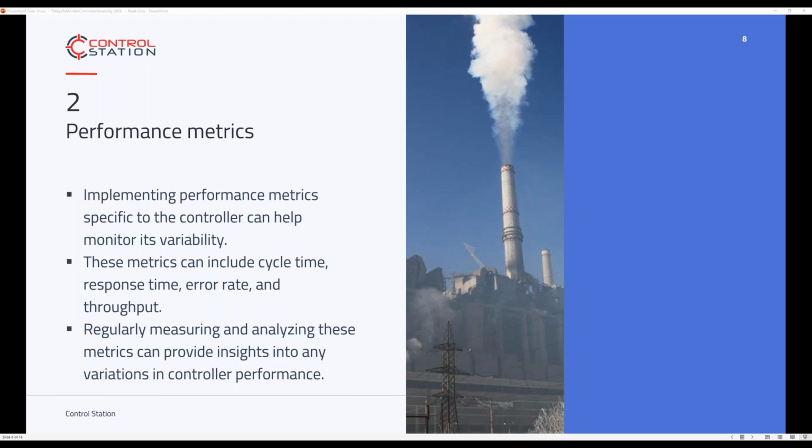That being said, we've also invested a lot of time in more advanced KPIs. Again, using the same tags, but looking at frequency analysis to determine oscillation in the loop, or doing thousands of lines of code to calculate a very reliable stiction metric. So you can say, oh, these are the valves that are sticking. These aren't. Even going so far as to use our advanced modeling capabilities to identify process models to recommend tuning ranges. Oh, your tunings seem to be outside of what we would recommend for a given loop.